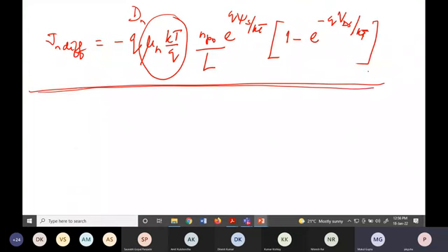Now if you increase this VDS, this term will be very low, because kT over q is 26 millivolt, you see. So VDS of 100 millivolt means maybe e to the power -4. So this part will go. All it depends on exponential q psi s by kT. And it is possible to show that Vg and psi s are kind of proportional.